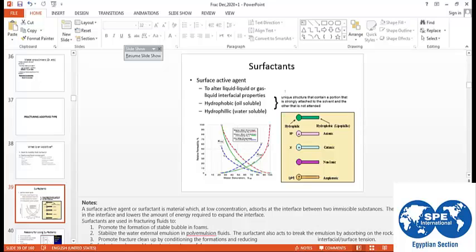So what is the required concentration of non-emulsifying agent to prevent formation of the emulsion? The concentration of non-emulsifying agent should be selected during this test. Also for the gelling agent concentration and breaker concentration selection.